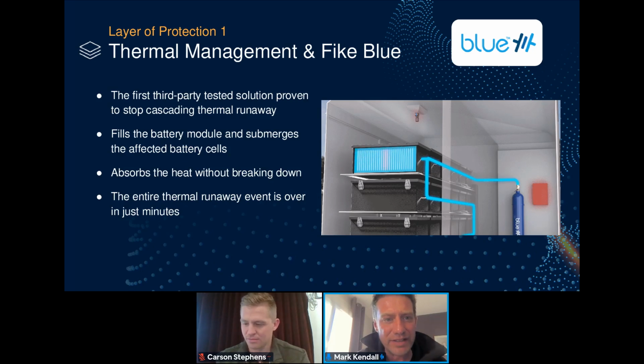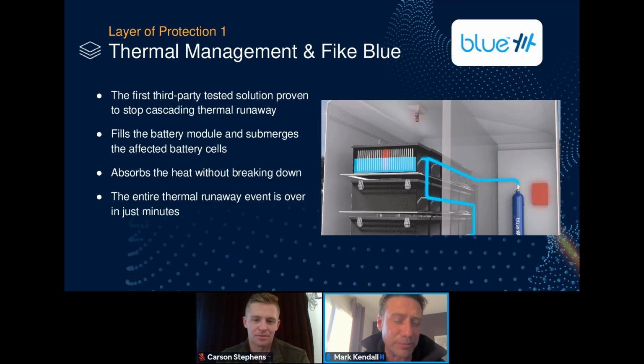So ideally, we want to stop what actually is causing the problem rather than treating the effects. We need to get to the root cause. And the root cause is really that thermal propagation through the battery module. So layer of protection one that we would look at is thermal management.